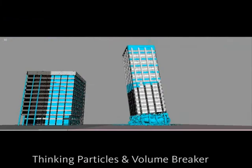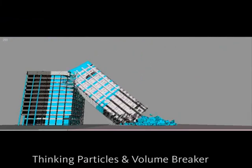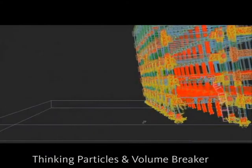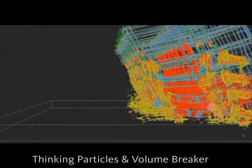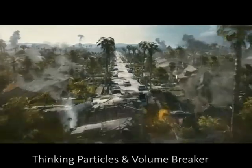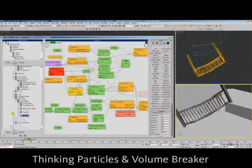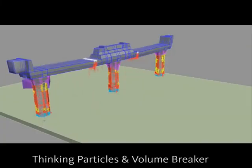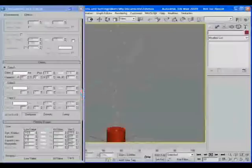Thinking Particles is a rule-based particle system that can achieve very interesting effects based on rules rather than events like in pFlow. This means that particle effects are done without any manual keyframes, so that any changes and iterations in the particle system are very quick to operate. Volume Breaker complements the particle tools by creating fragments from scene objects to turn them into particles.